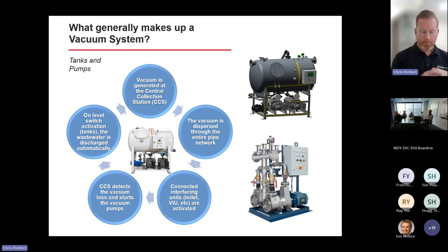Essentially, from day one, when we have a project, before we've turned it on, the pipe inside and externally are all at atmospheric sea level pressure. Then when we start up that vacuum plant, we start some pumps that pull the air out of that pipe network, and so we start to create a subatmospheric condition. That air is being transferred out to external vents. Once we get down to a certain vacuum point that the plant is designed to maintain, the pumps shut off. They don't run all the time. Then we have a subatmospheric condition.